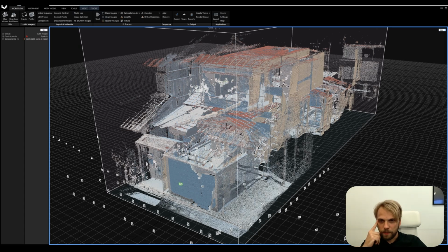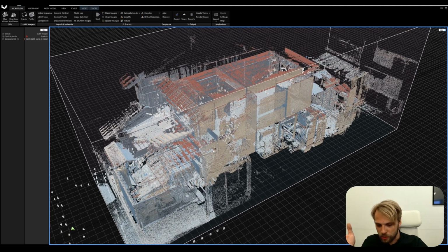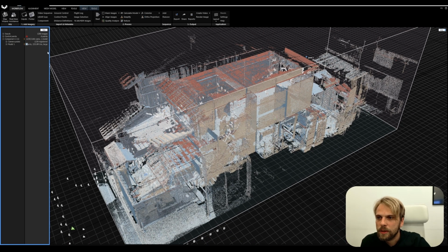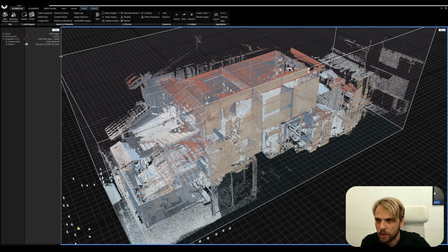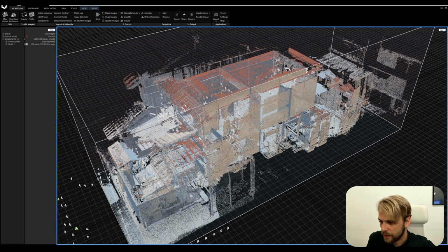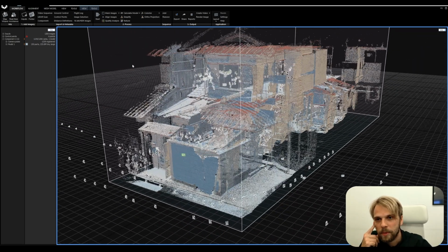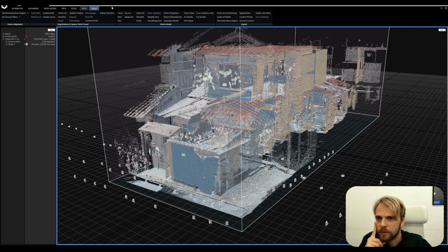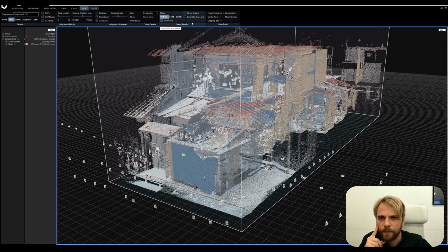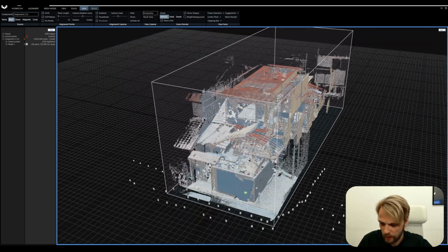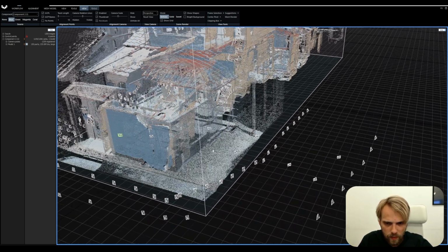All right, there we go. So right now what we see here is a dense point cloud, and that's because the resolution of the mesh is too high. Actually, if I look at this, 233 million polygons. There's no way that my graphics card can actually show the whole mesh, but there's a trick. If I go to the scene 3D view, right around here, we have the clipping box tool that I can use.